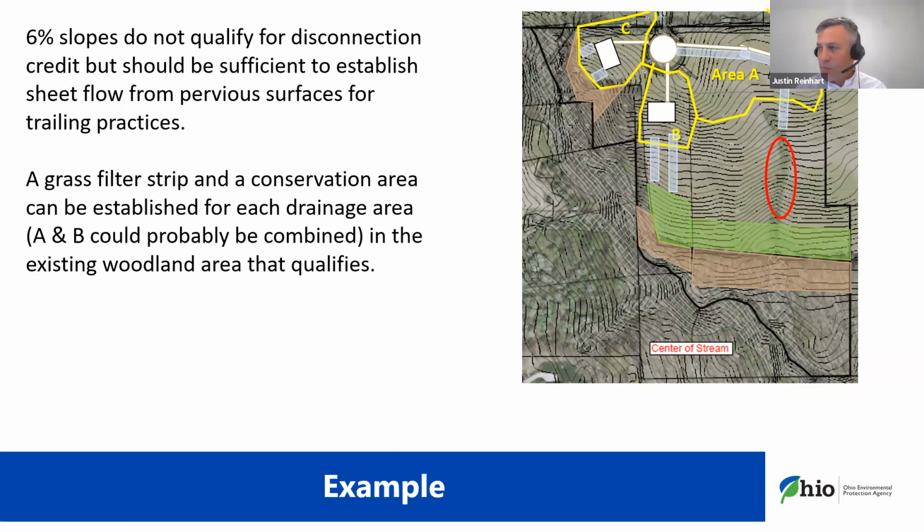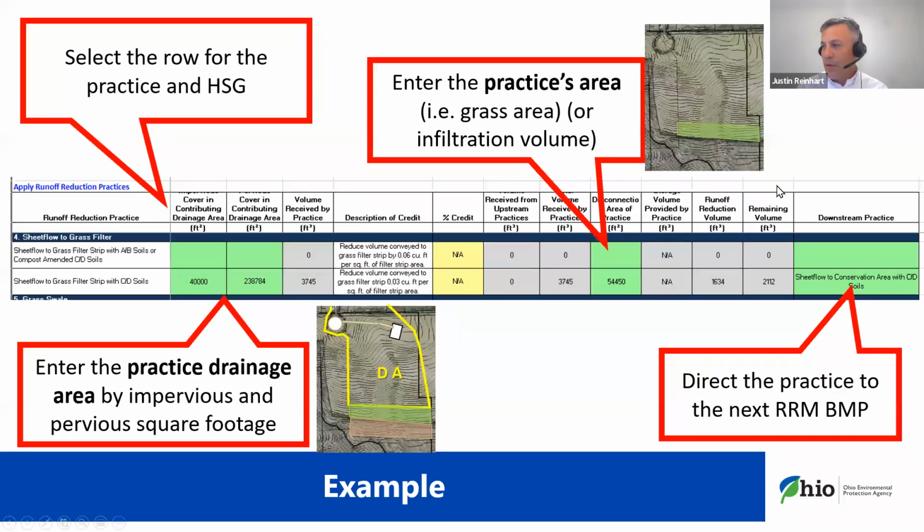The one thing I'll note as I re-step through this is, this was a bit of a challenge, admittedly, that you have a convex sort of, or I should say, I just get those confused, more of a concave type scenario here, where you have a funneling situation, and all this runoff is really coming into maybe not being distributed as sheet flow, but coming really more of a concentrated area, although it's not really channelized. And we had discussions about trying to even that out to help encourage this be more of a flatter terrain and provide more sheet flow into these areas. So we really should be avoiding that as much as possible.